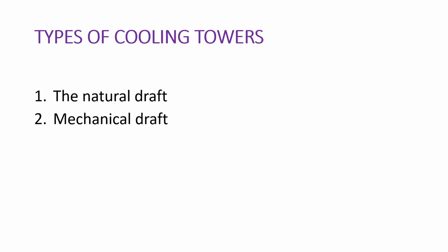With the mechanical draft, we are using mechanical devices like fans, pumps, and other mechanical devices. So here we use mainly fans to move the air. So fans either push the air or pull air. So the advantages of mechanical draft cooling tower are that it is more compact, has better control, and higher cooling efficiency. However, it has two disadvantages: it requires electrical power and has higher maintenance.